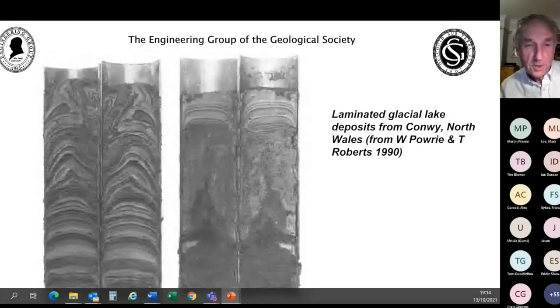A couple of things to note in passing are the extreme distortion in this so-called undisturbed sampling tube, especially where there is a stone in the material, which is the case about the middle of the left-hand split. And then near the bottom, we run out of the laminated structure, and it becomes much more amorphous. So this was the one that had to be controlled with the ejector wells, and they applied a vacuum to assist with the removal of groundwater and the control of pore water pressures in this stratum. Next slide, please.